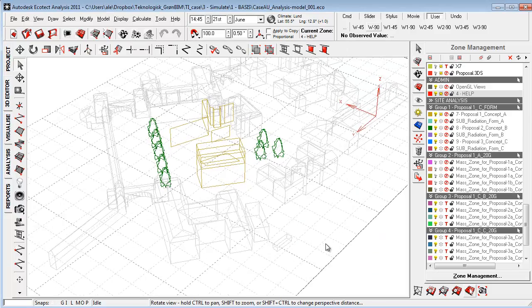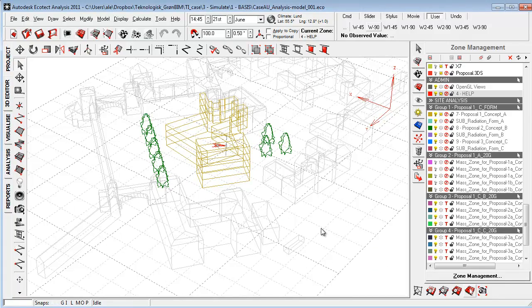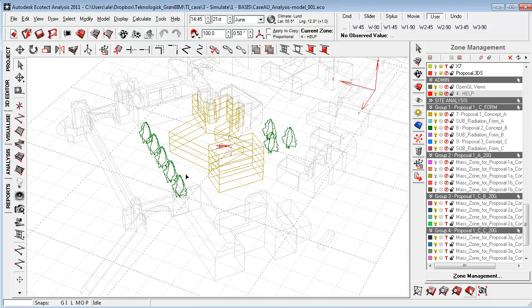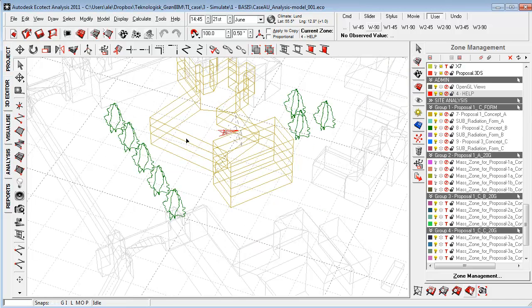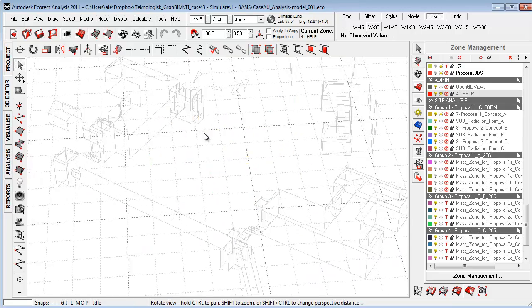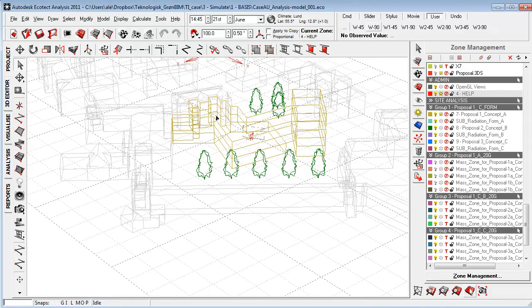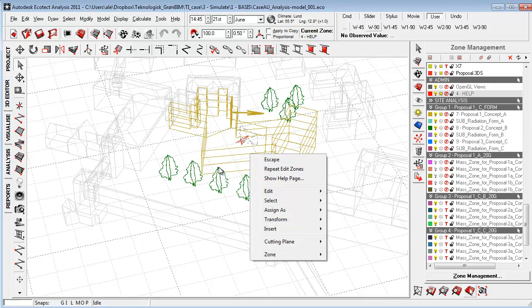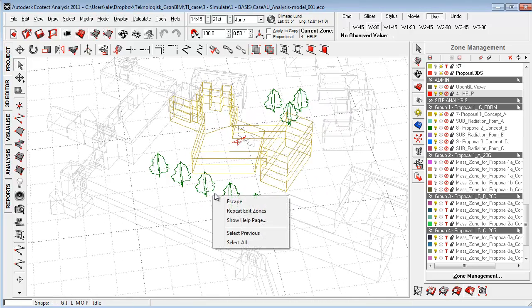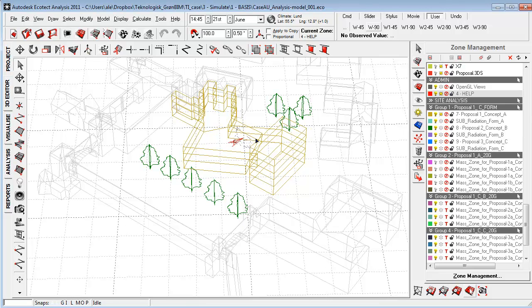So depending on which type of analysis, it's really different outputs that you'll need to pull into the model. So it's really important that the geometry is working the right way, no matter if you're doing a thermal analysis, shadow calculation, or acoustic simulations, or whatever. You need to make sure that this directional arrow here from each surface in the model is pointing from the inside to the outside. That's a very important parameter here, and I have explained that in another video on the website here.